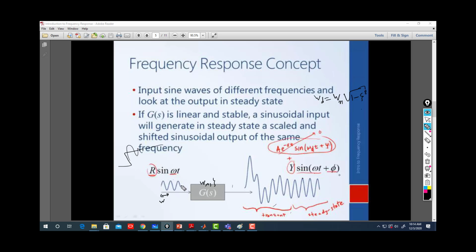And there is a phase shift compared to the system, and A is some amplitude, times e to the minus sigma t. With time, you have this attenuation. The sigma, if you remember, is the attenuation, related to the settling time. It's the attenuation of your curve, your envelope. That's the sigma, if you wish. But we consider this part negligible. It's like saying I will consider my sigma equal to 0. So I'm neglecting the settling time.